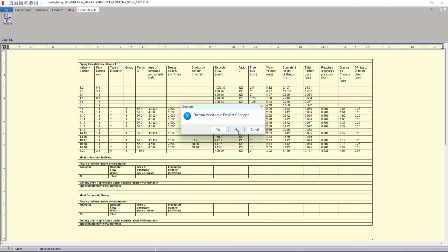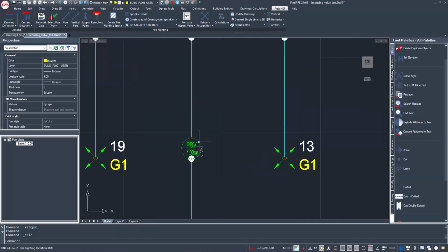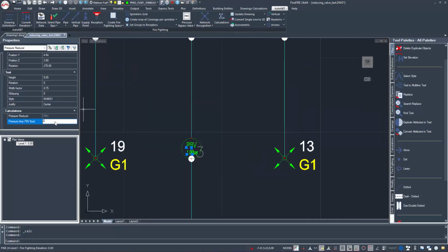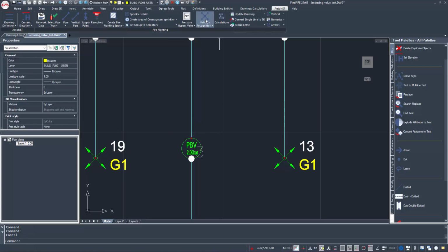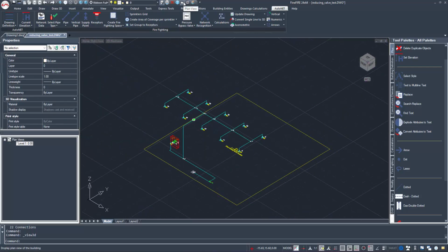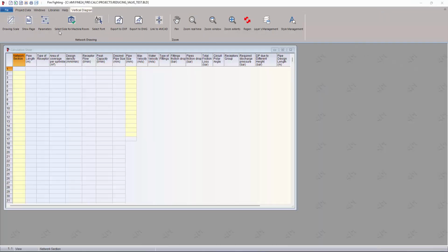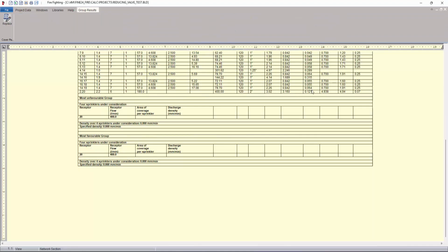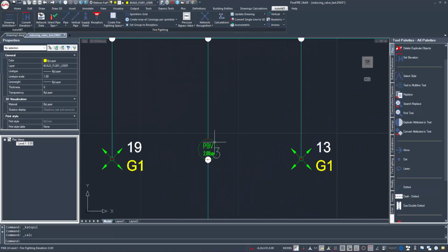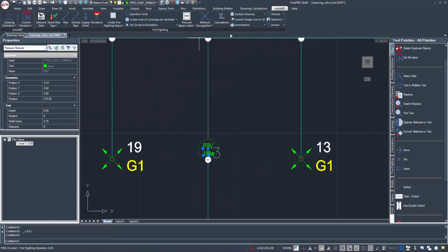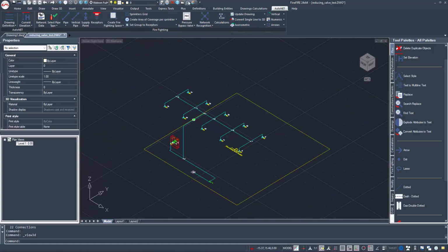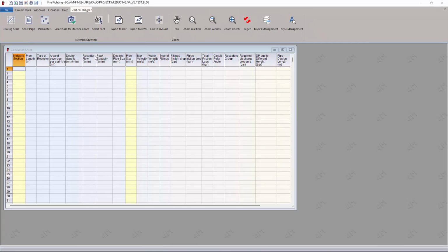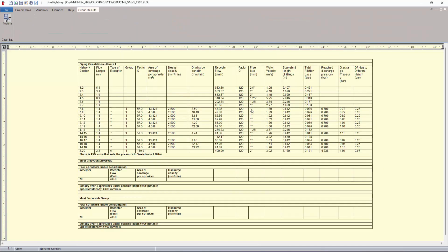We will assign a different value to the valve. This can be done by going back to the CAD environment, clicking on the valve and scrolling down on the Properties tab. From there, we can assign a new value. Once again, we use the same procedure to move to the calculation sheet. We repeat this process, until the desired value is found. With a pressure drop of 2.6 bar, we observe that we are getting very close to the desired outcome.